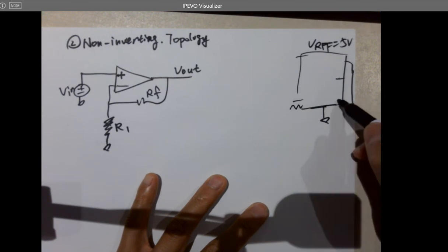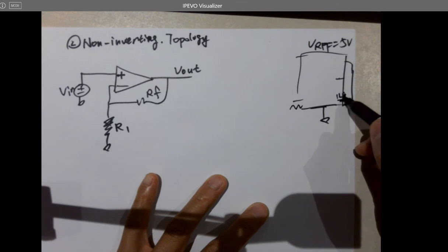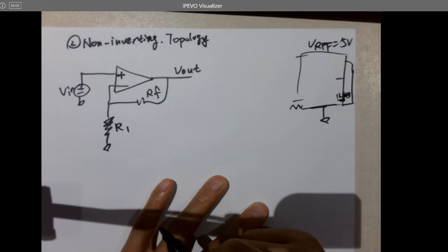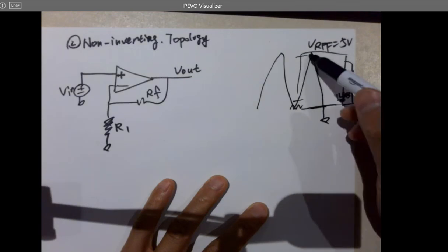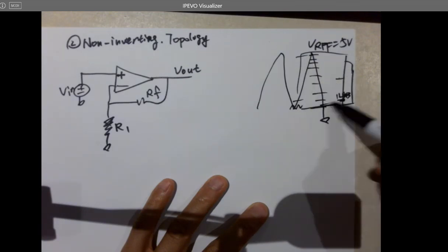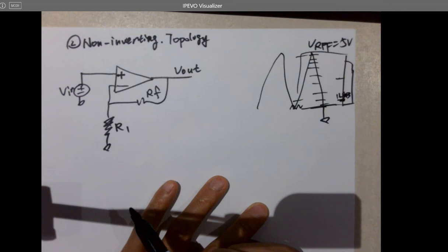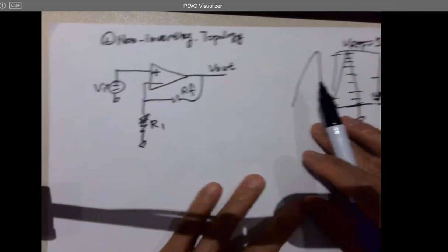It's always giving you 1 LSB. And you are trying to sense something, but you are getting nothing. So you want to amplify this guy into this full range, right? So you can resolve it step by step. So you can sense the changes. Make sense? That's why you need amplifiers to amplify the voltages.